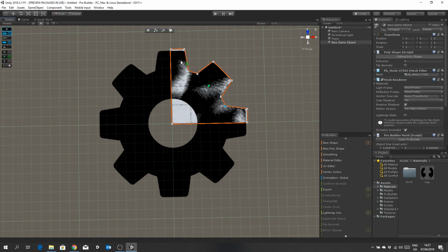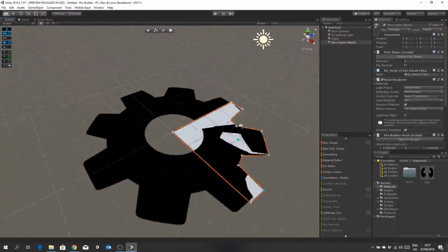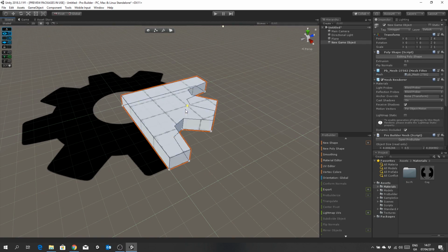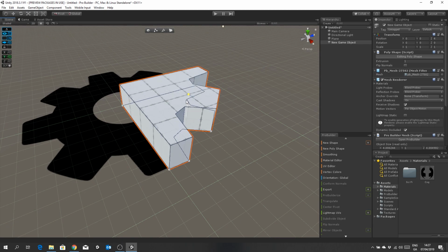Okay, so that's kind of the base part of the geometry ready. I might just pull that in a little bit. Yeah. Okay, and now I'm going to rotate it out. And what you can do is grab this lovely little gizmo here, and with grids on again, if I drag this up, it should snap to whatever increment or grid increment I've specified up here.